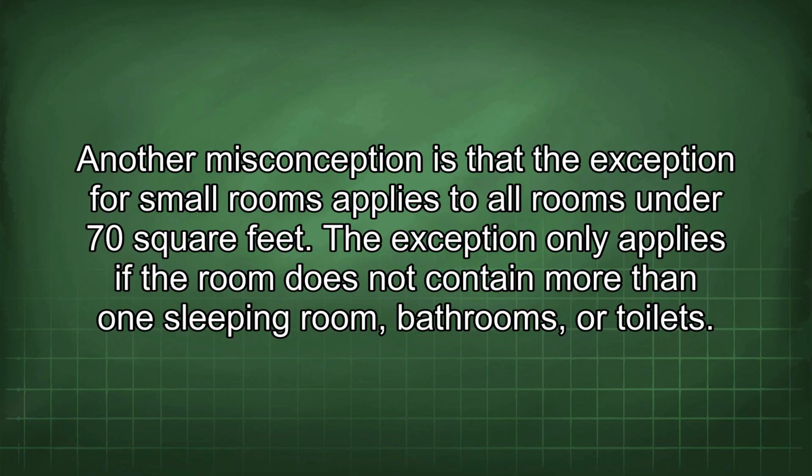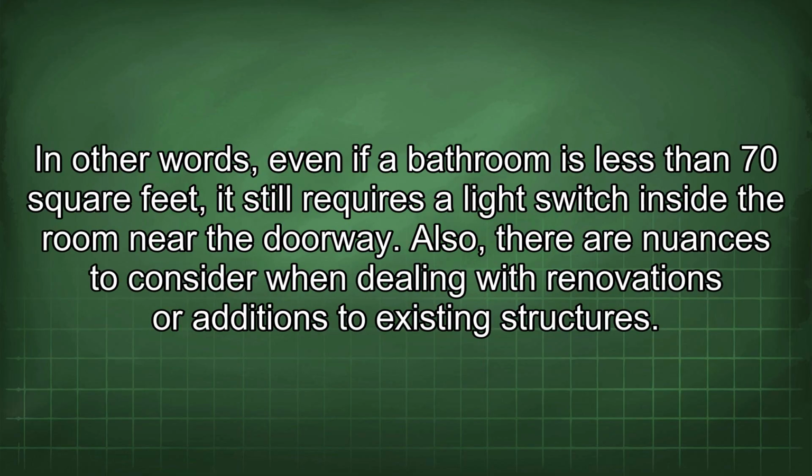Another misconception is that the exception for small rooms applies to all rooms under 70 square feet. The exception only applies if the room does not contain more than one sleeping room, bathrooms, or toilets. In other words, even if a bathroom is less than 70 square feet, it still requires a light switch inside the room near the doorway.